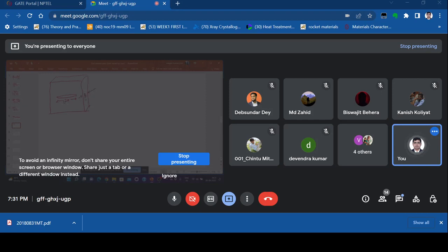This is the full crack length 2A. So suppose gamma is the surface energy per unit area of one surface. So what will be the surface energy required, total surface energy? So this is one length is 2A, other is 2A. So 2 times 2A into our thickness B into gamma S.